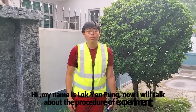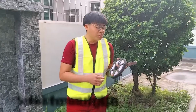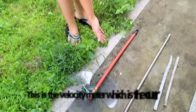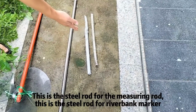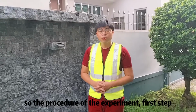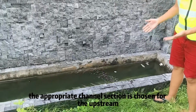Hi, my name is Lo Yan Fong. Now I will talk about the procedure of the experiment. This is the measuring depth, this is the hammer, this is the velocity meter, which is the current meter, and this is the steel rod for the measuring rod. This is the steel rod for the river bank, and also the life jacket. For the procedure of the experiment, first step, the appropriate channel section is chosen for the upstream.